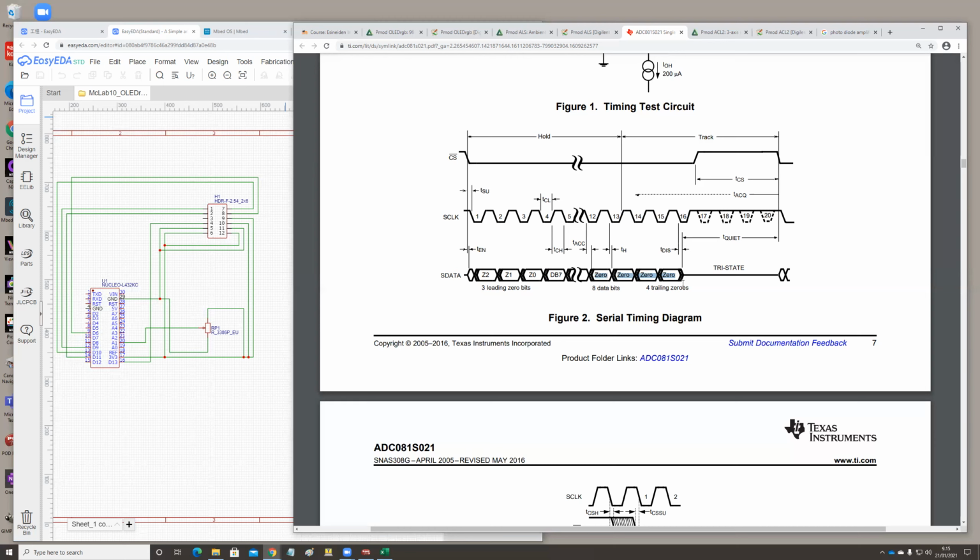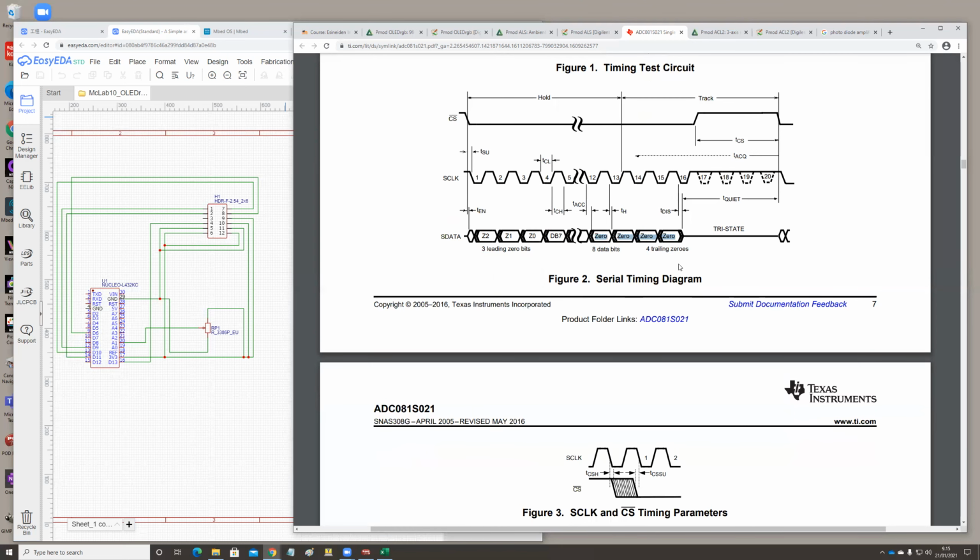Because you communicate either with 8 bits or with 16 bits in the SPI interface. So you are filling the memory of the microcontroller, and the memory is always referred to with 8 bits. So you get an 8-bit and an 8-bit piece of information in there. But from that information, we need to somehow get the bits out from the center, because these data bits are there in the center.